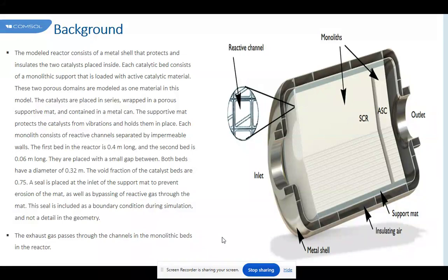In the TWC, nearly 60 to 85% of the cumulative emissions occur before the converter light-off, which takes about 10 to 18 seconds, depending on the catalyst loading, location, and other factors. This length of time also depends on the thermal capacitance of the converter and the exhaust gas temperature and velocity at the inlet of the converter. Metallic substrates have a higher heat capacity compared to ceramic for the same volume, but the total thermal capacitance of the metallic monolith may be comparable or lower compared to ceramic monoliths due to the thin walls.